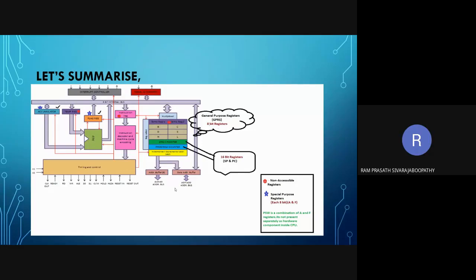I have one more question. Depending upon the size of the instruction, the PC is going to increment, right? Yes, sir. Let's say I have a 3-byte instruction, LXI B, 2000. I'm not sure about the opcode of LXI B. Let me say it is 21. If I have to feed the data, how will I enter? In one memory location I will enter 21, then 00, then 20. That's how I enter, right? The opcode is 11, sir. Okay, 11, 00, 20. That's how I enter the opcode into my kit, right?